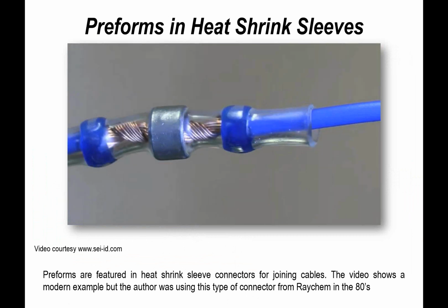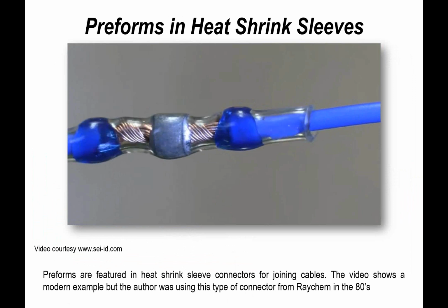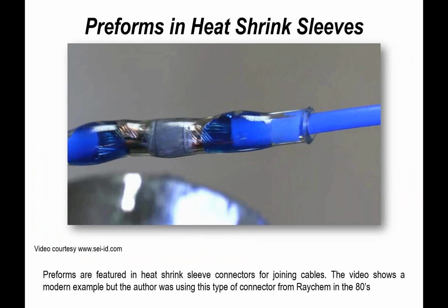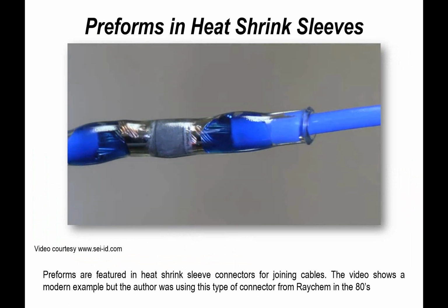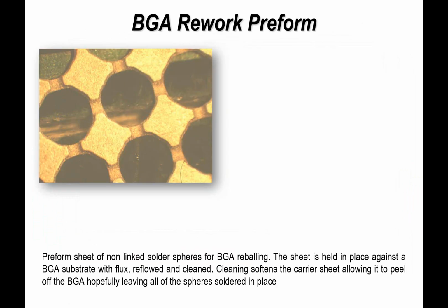And what you're looking at now in video, it just shows the solder reflowing, bringing together the multi-stranded cables, reflowing, and some suppliers of these sleeves have a colouring agent which change colour when reflow has taken place or a certain temperature is actually reached. These are very elegant today. Our preforms that we used were not quite as elegant as this, but fundamentally they worked exactly the same and proved to be extremely reliable as a process.